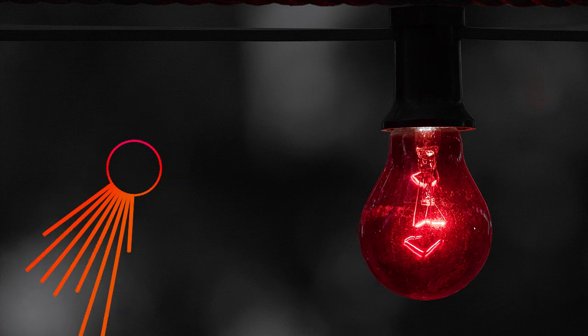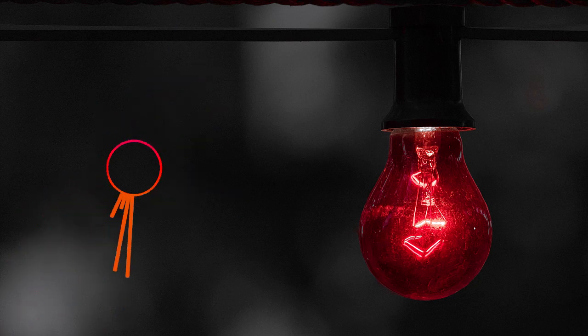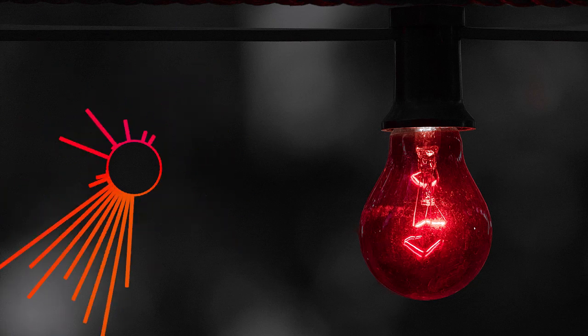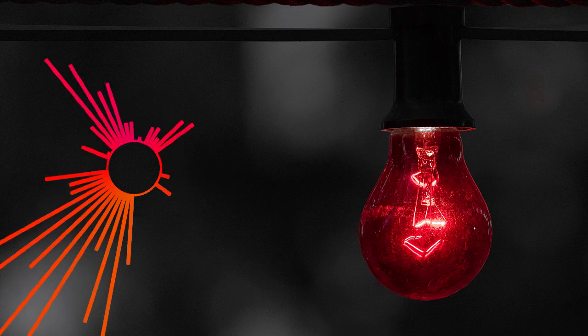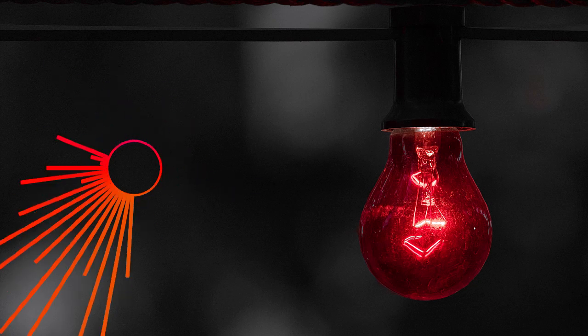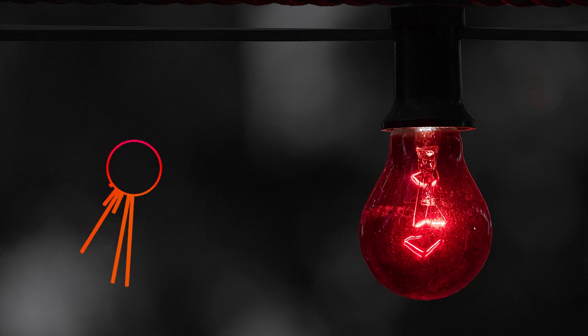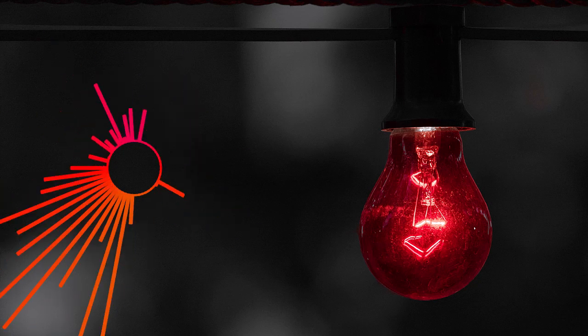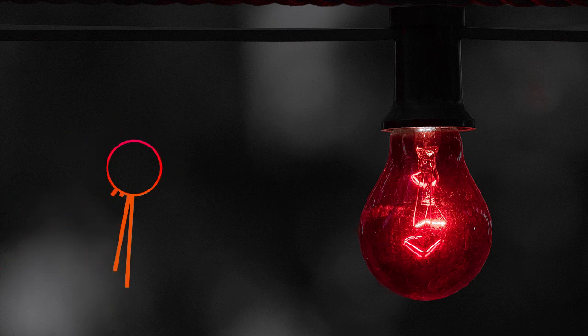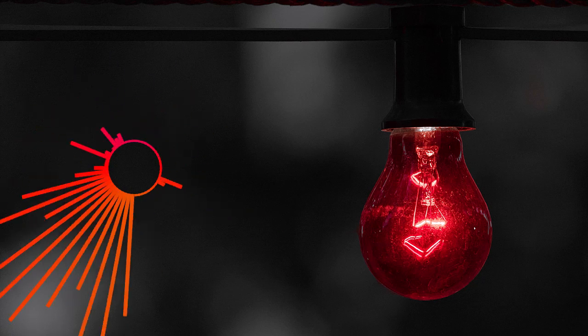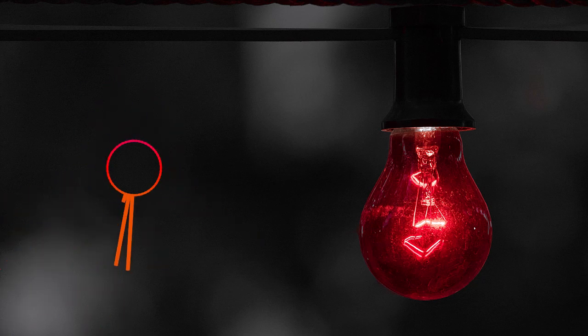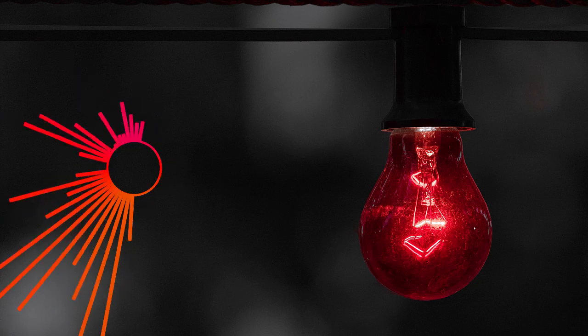Let's wrap it up with a big picture. Electricity flows from a generator into the building's main panel through lighting circuits made of conductors and into lighting systems which convert that energy into light. Lighting circuits must be carefully designed to match the load of the system, using the right wire size, circuit breaker, and the number of luminaires.